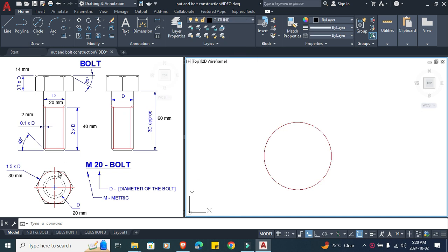Now, around this circle, you draw a hexagon using the polygon function. Select polygon, come back on screen, type 6, press enter. Now, moving the cursor towards the circle, as the center lights up, you lock it in here. Left click once, use circumscribe, and come downward. For this, you can make sure your auto mode is on. At this point, you drop this hexagon in place.